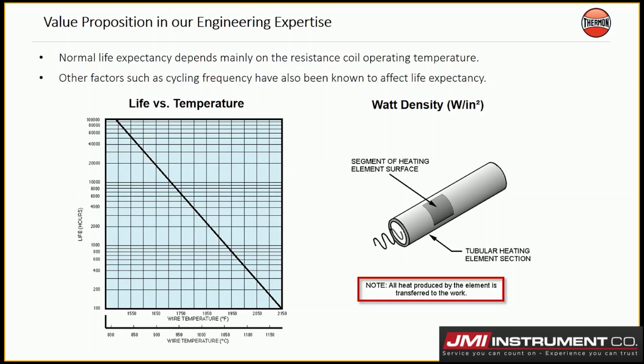Now you'll ask why. Why do we limit the watt density? Why are we concerned about watt density? Why are we concerned about the viscosity of the fluid? High watt densities will generate high sheath temperatures, and these high sheath temperatures can burn processed fluids. For instance, bitumen will burn quite readily if we run higher watt densities, because the sheath temperature is just simply too high for the fluid to receive the heat.